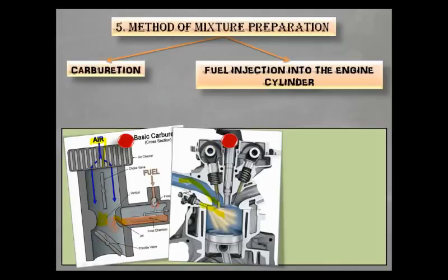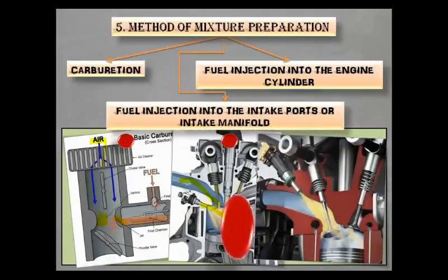Third is fuel injection into the intake port or intake manifold. In this, the fuel is injected just above the intake port. This system allows, or let's say provides, more time to fuel and air mixture to get mixed homogeneously, as we can see over here in this picture.